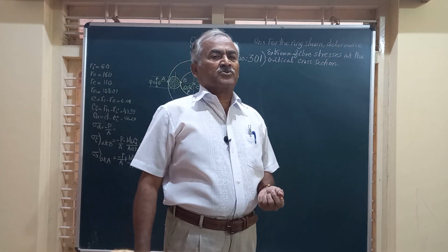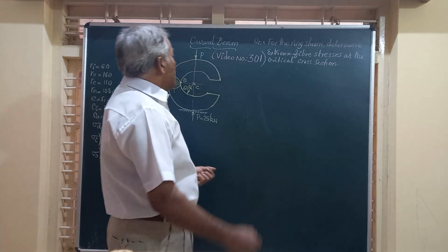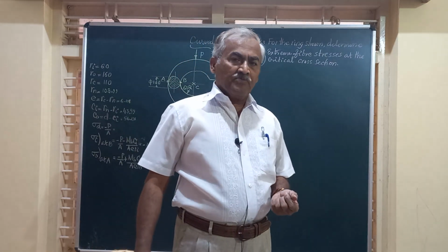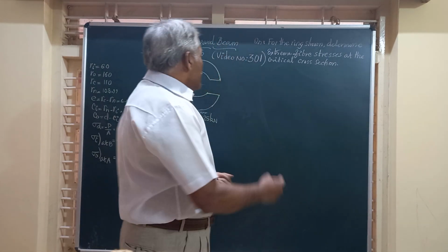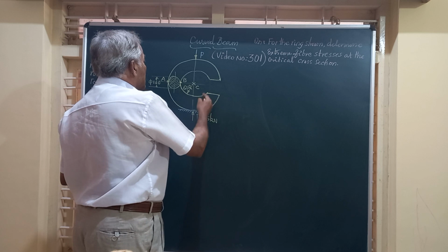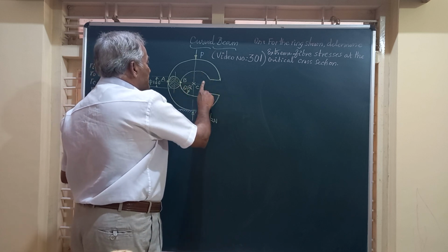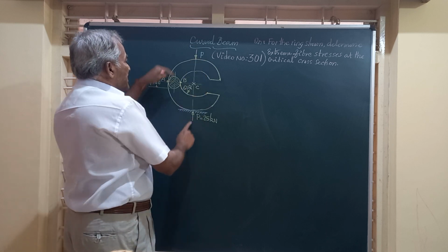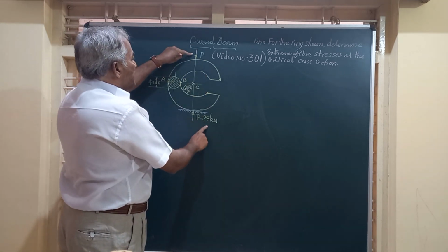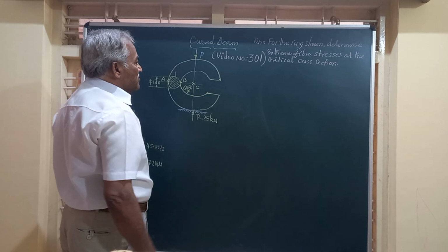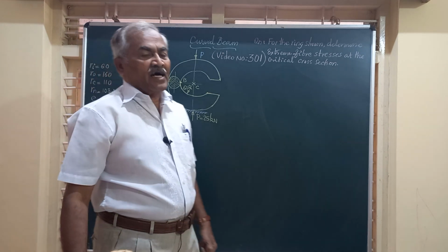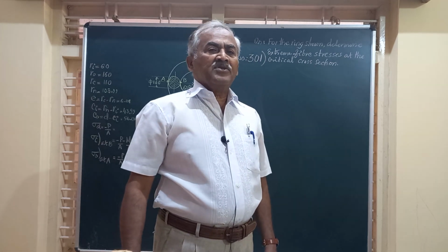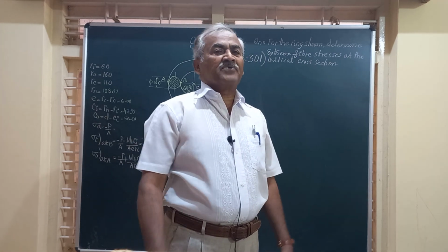And friends, in today's video, we will work out a problem on the application of a curved beam, wherein you have a circular ring which is open and it is of circular cross section and it has been subjected to a load of 25 kilonewton. This P is 25 kilonewton, and we have been asked to determine what are the values at the extreme fibers